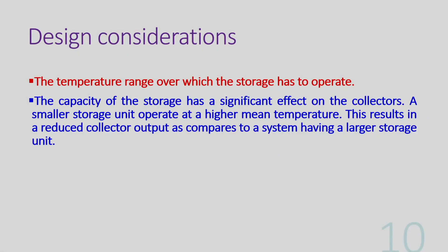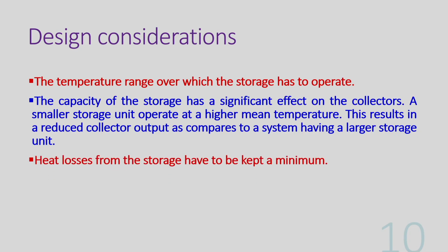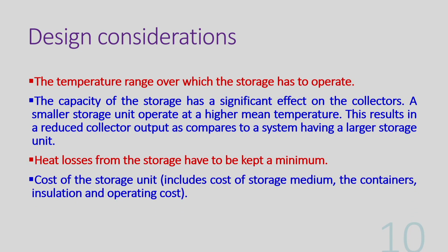The capacity of storage has a significant effect on the collectors. A smaller storage unit operates at a higher mean temperature. This results in a reduced collector output as compared to a system having a larger storage unit, and then heat losses from the storage have to be kept at a minimum value. And finally, we must see the cost, which includes cost of storage medium, the containers, insulation, and then operating cost. So, these are the design considerations.